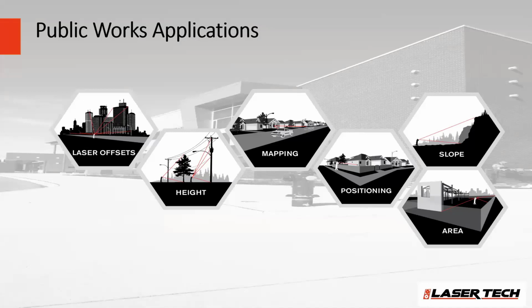Now that you've seen a little bit what the lasers do and what some of the solutions that pair with these lasers can offer you, what kind of industries or what kind of applications do these lasers have a real nice fit into? In public works, we have a big following on laser offsets and heights. You can stand someplace safe and get the measurements you need without putting yourself in jeopardy. A lot of the public works folks have to map out every fire hydrant, every gas meter, every opening in the road, and this allows that mapping to happen safely off the roadway without having to stand in the middle of a road with a GPS receiver.